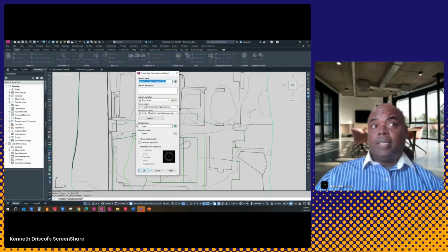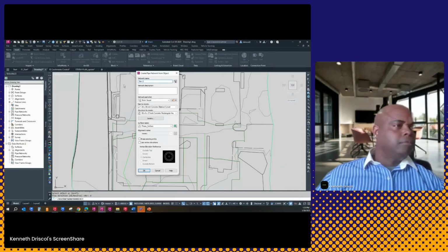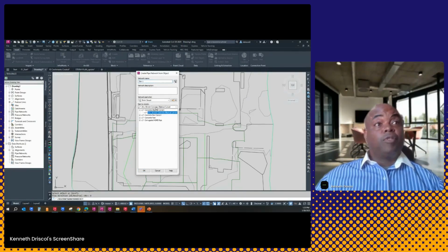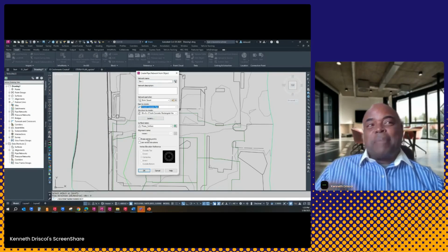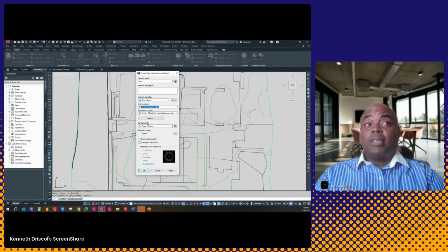and we'll select OK, same process. This is critical. So still storm 1. And then, of course, 12-inch pipe. And the size of pipe doesn't even matter because I'm using it as a conceptual layout to get to InfoDrainage for my design.